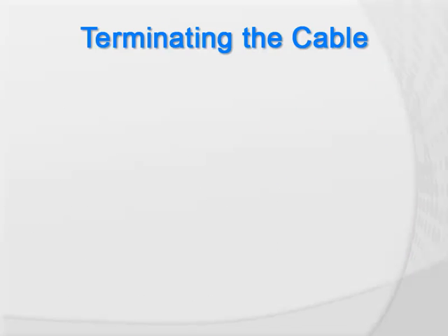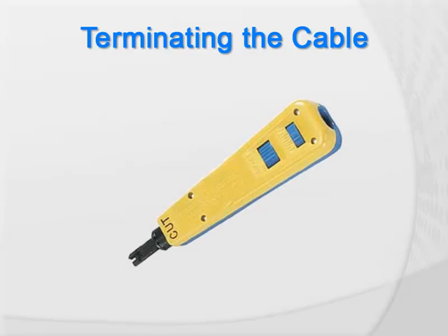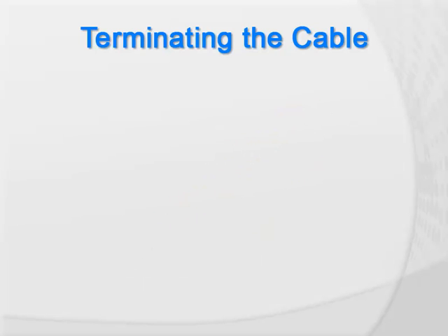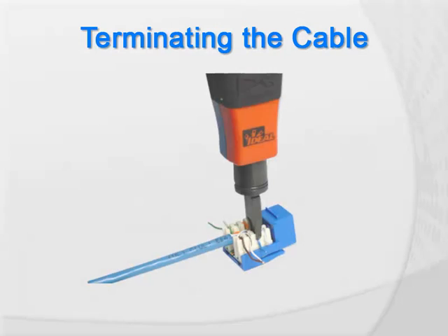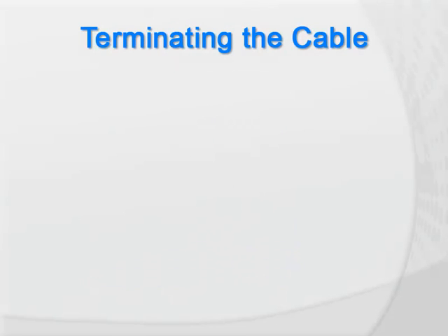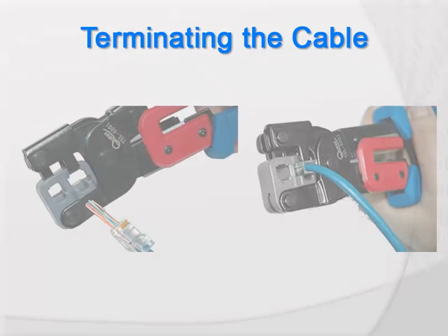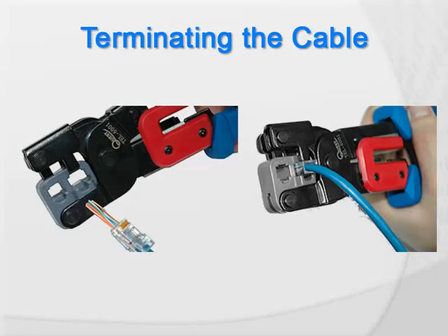The UTP cable terminates into the female RJ45 connections using a special tool called a punch-down tool with a 110 blade attachment. These can be found in any decent hardware store or electronics supply house. The punch-down tool is required to properly press the solid wires into the slots and secure a good connection. Male ends are placed on RJ45 cables using a special RJ45 crimping tool.